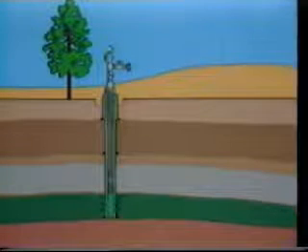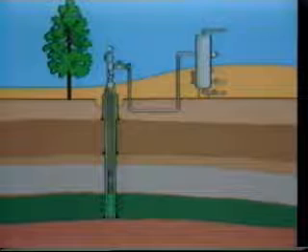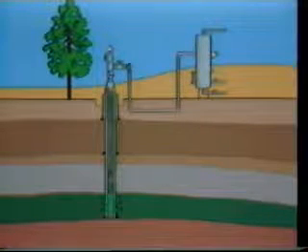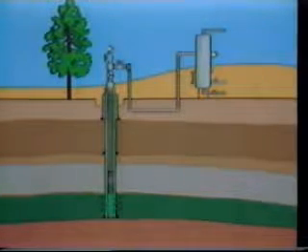So far, we have learned what surface and subsurface equipment may be needed for producing a well, but we haven't yet learned how a well's production rate is related to the pressure at which the fluids will be produced. This is the objective of Unit 2. We begin our discussion by dividing our producing well system into its major components: the producing formation, tubing, choke, surface flow line, and separator. These elements are sufficient to illustrate the concepts involved in describing the pressure flow rate relationships of our production system. All of the components are interrelated.